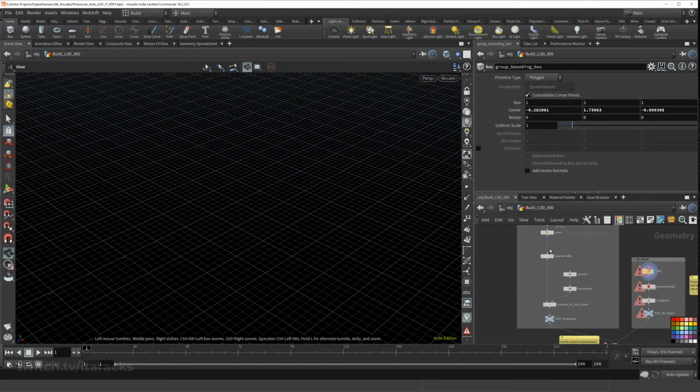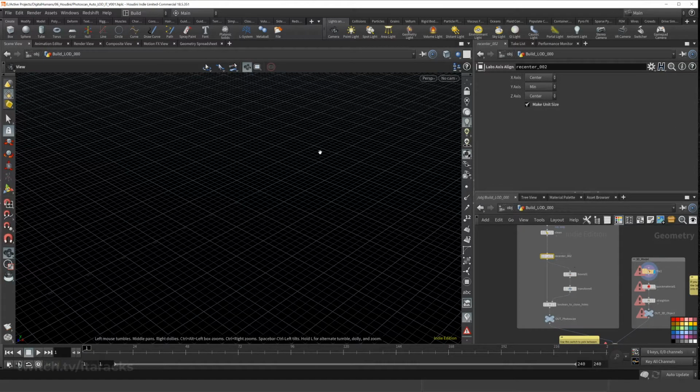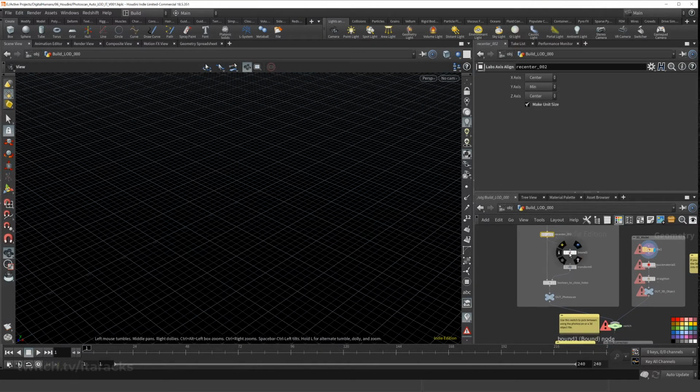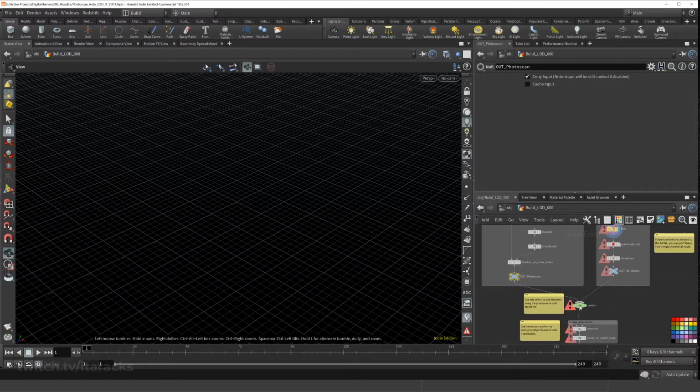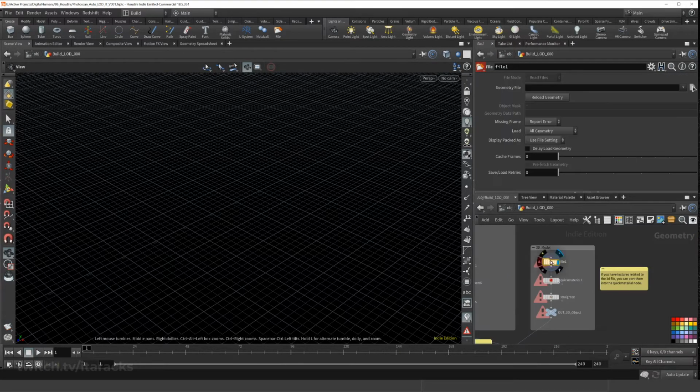It goes through and uses another SideFX Labs node to recenter to world origin. After that, if there are any holes in your scan, you can use the bounding box to do a Boolean operation for intersection to easily close all those holes. Then you are left with your out photo scan null that will go into the switch. This switch just notes how you will pick between which method you want to go with. It's much easier here for the 3D object method.